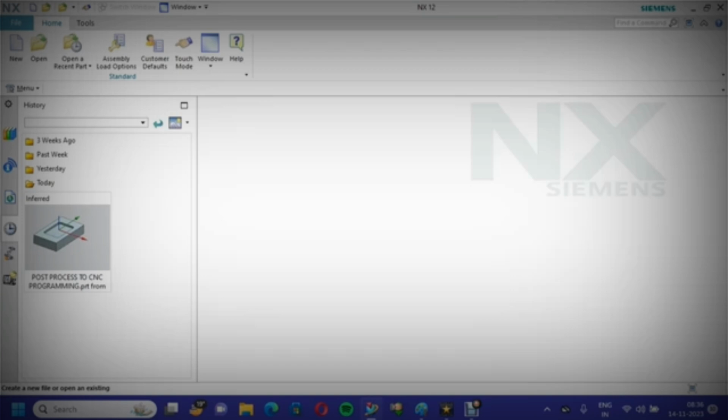Somebody is having Fanuc control or Heidenhain or Siemens control. According to your control, meaning your machine controls, we have to create the post processing. Then we can edit the post processing as per your machine requirement. In this case also we have to do the model and create programs. Then I am explaining how to do post processing and editing the program for your machine controls.